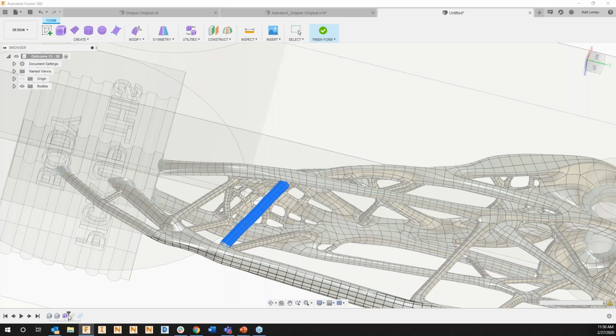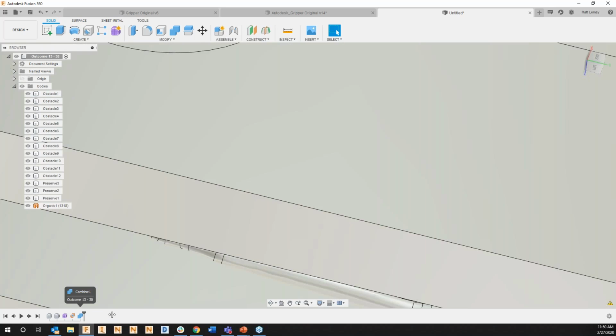So the final thing that I wanted to talk about here is we took a generative part that we had applied loading conditions to, all of these different manufacturing constraints, and we actually made an adjustment to that part after we sent it out. So how do we know that this part is actually still within compliance? So what we can do within Fusion 360 is that once we've generated an outcome, we also have the simulation workspace to actually validate any of those changes very quickly.